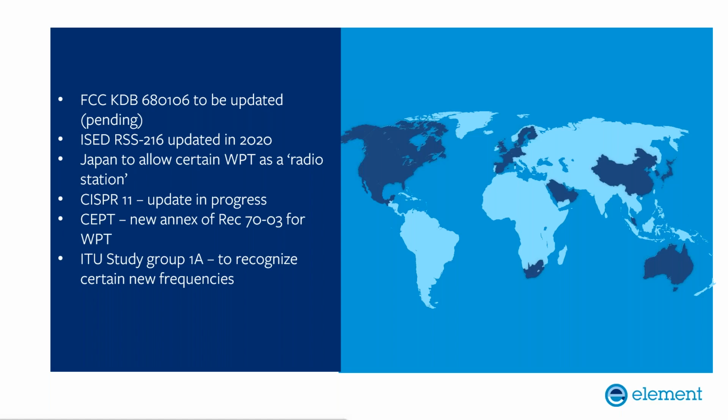CISPR 11, which I was referring to earlier on, has got a number of updates in progress. Essentially, they fall into two categories. There is a project that is looking at the low frequency side, specifically on electric vehicle charging. And there's another project, which is the UHF side of things, where they're looking at beam type WPT, where you can use it at a distance. And that standard will hopefully be updated towards the end of this year or during the course of next year.